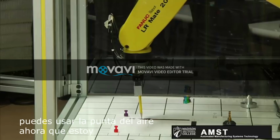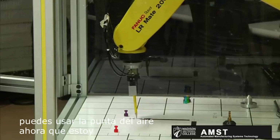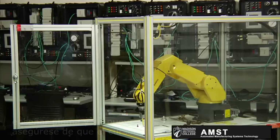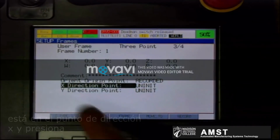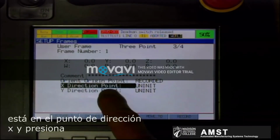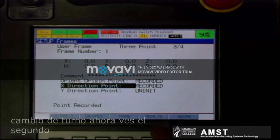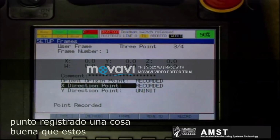I'm going to use the tip of that arrow. Now that I'm at the tip, I'm going to show you the teach pendant again. Make sure the cursor is on the X direction point and press Shift, record. Now you see the second point recorded.